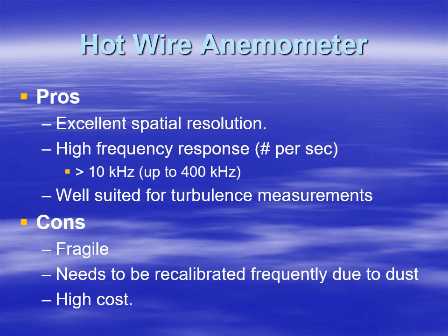So here are your pluses and minuses of hot wire anemometers. The pluses, of course, they have great spatial resolution. Also very high frequency response, on the order of 10,000 times per second it can get a value of wind speed. So they're very good for measuring turbulence.